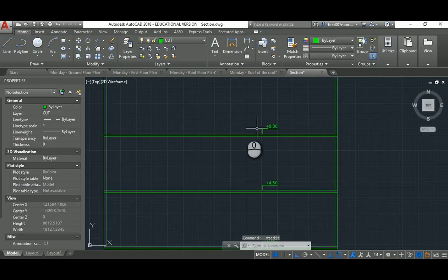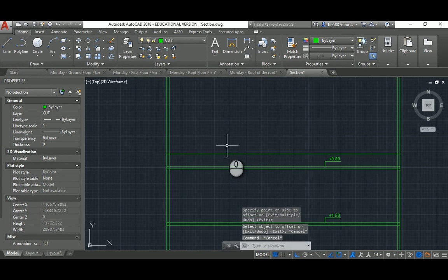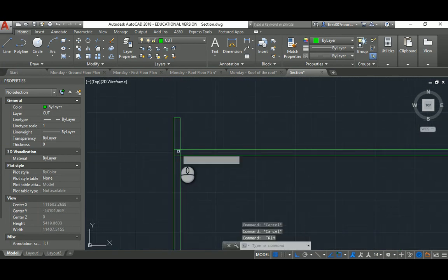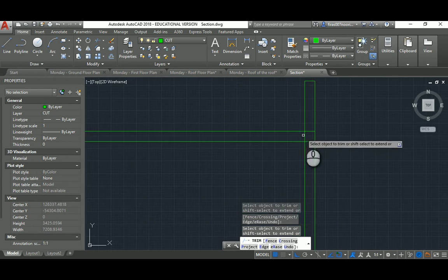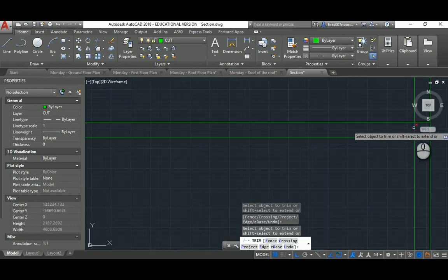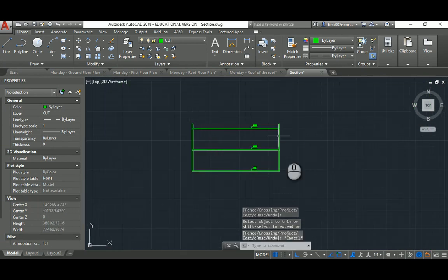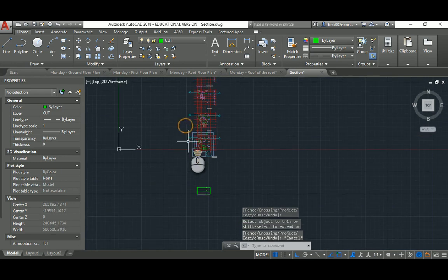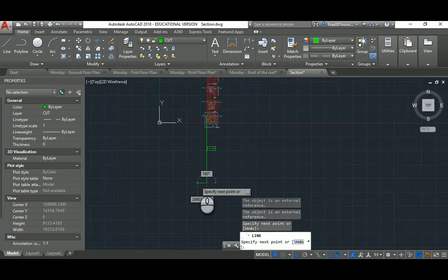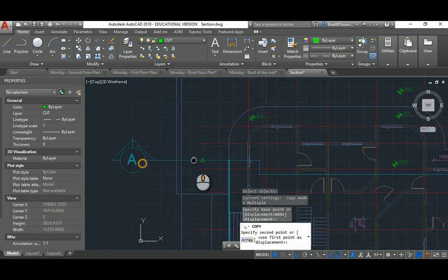Okay, and 1,000 offset, and then trim that to get the cut part of the external building. Forget anything you see in elevation, forget even the inside walls, just forget them. That's the building from outside. I'll continue the outside things while I'm here, so I'll take the walkway with me, and probably it's a good idea to finish the fence at the same time.